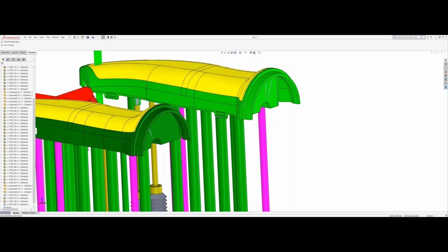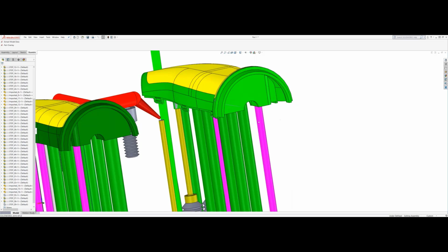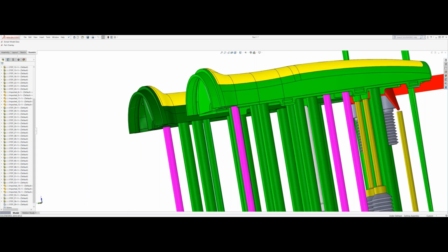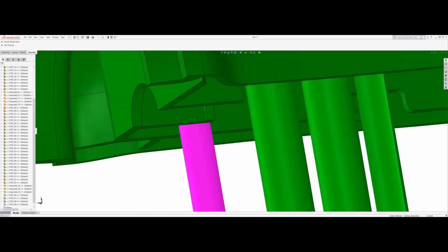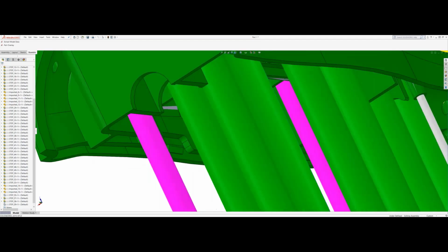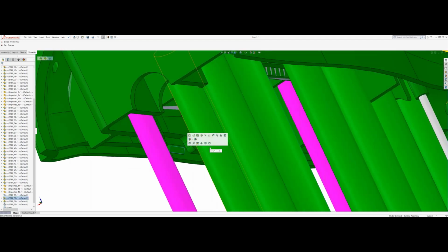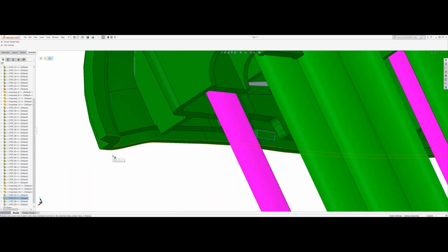I don't know if there's a specific name for it, but these would be created with actions on the substrate tool. So you would have a pull or a slide, on either side on this part, and then with the other one being on the interior of the part, here, you'd have internal pulls or lifters to create those.